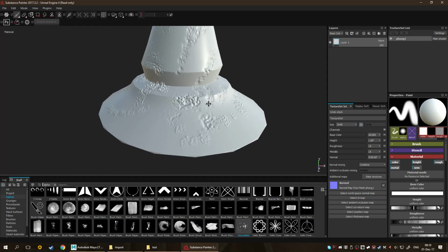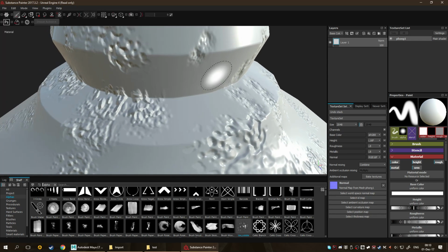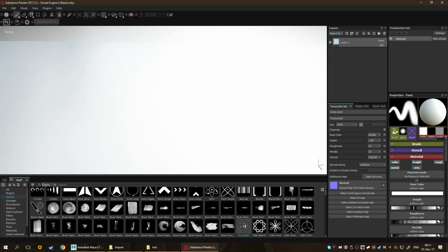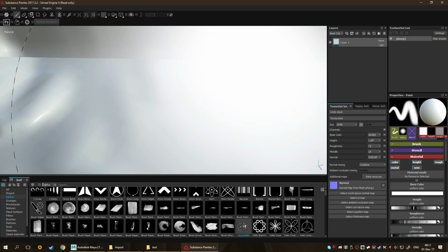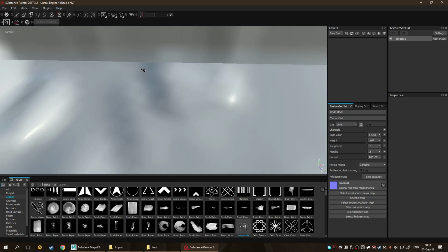Okay, so what do we have before? This is our bake here, and I should mention, by the way, that a lot of times you could get an artifact simply due to the fact that you're working with a non-infinite object, which is the texture. So our current texture on the normal map is 2K by 2K, right? It's 2000 by 2000, meaning that if I keep zooming in, eventually I'll start seeing these. Let me delete this guy. There we go. Now, eventually I'll start seeing this pixelation.